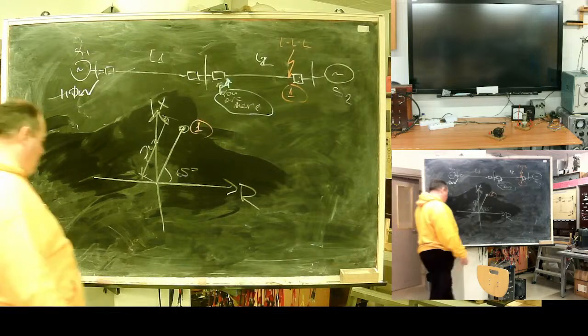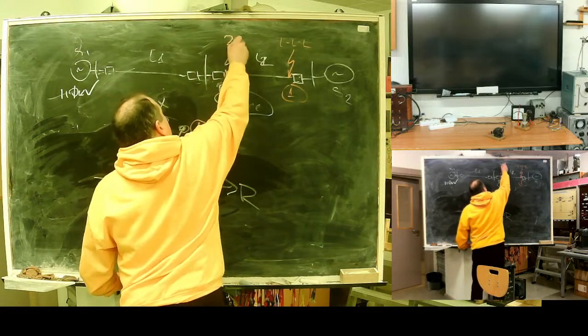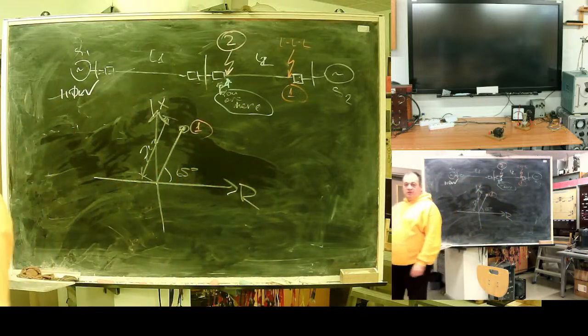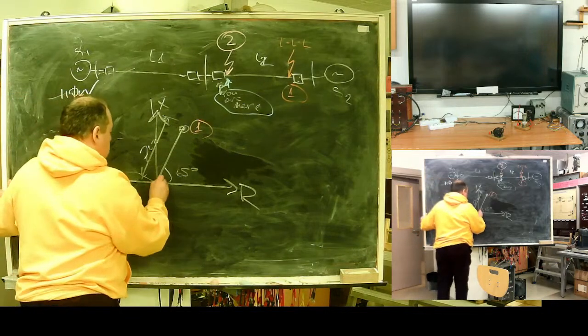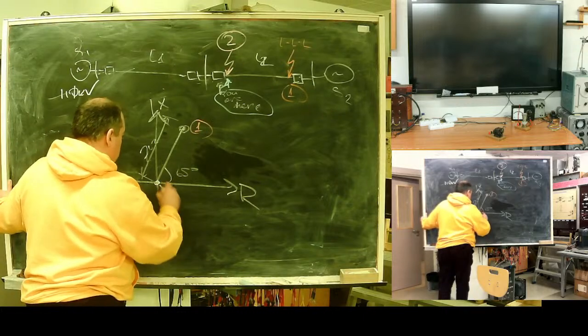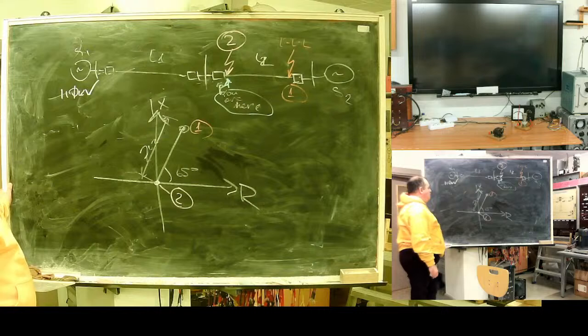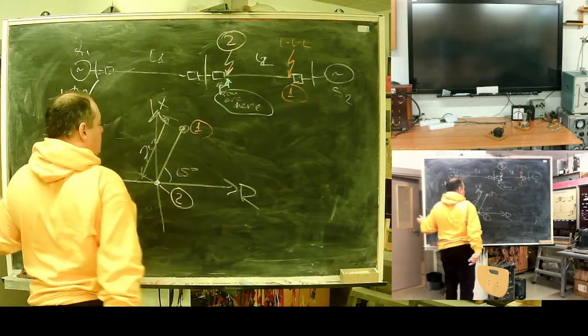Okay, more faults for the god of faults. Fault 2 at kilometer 0. What will my relay see? Answer: 0. Nice. So the area of operation is in the first quadrant.